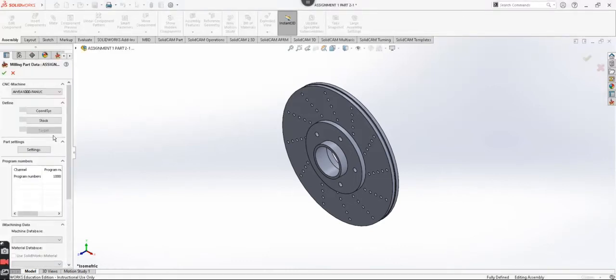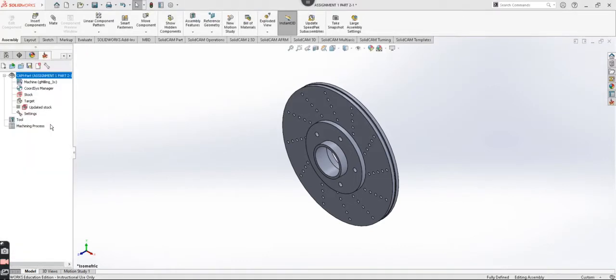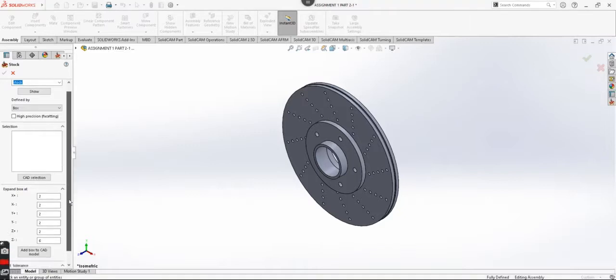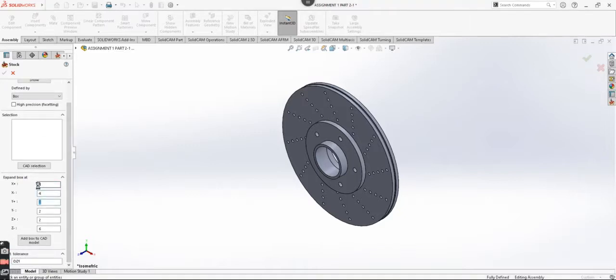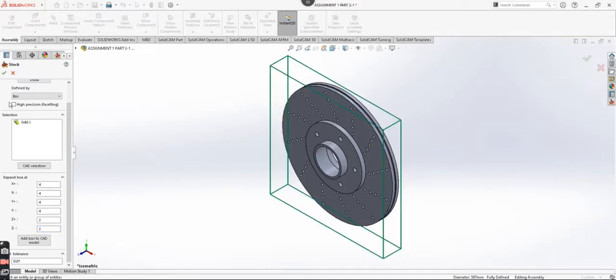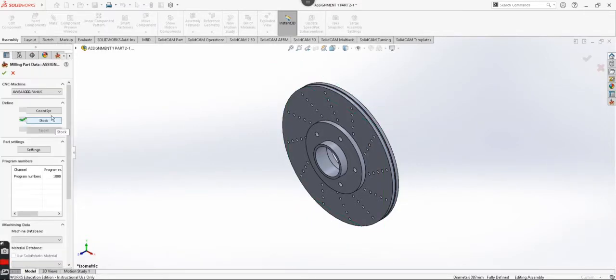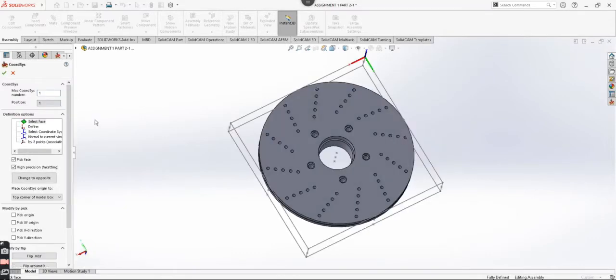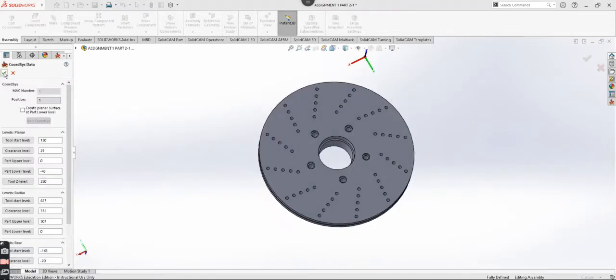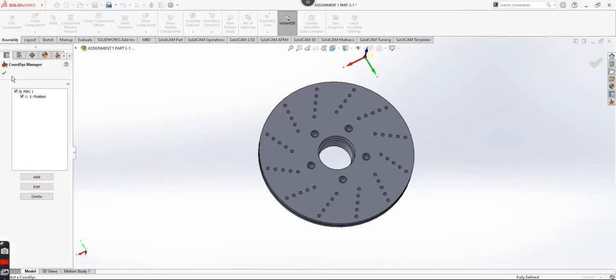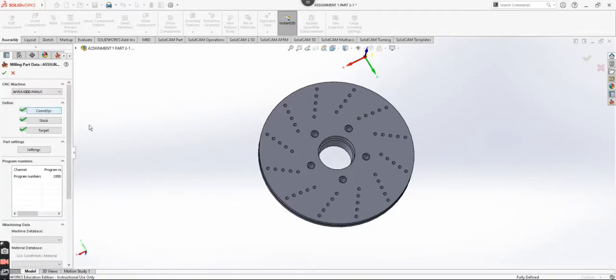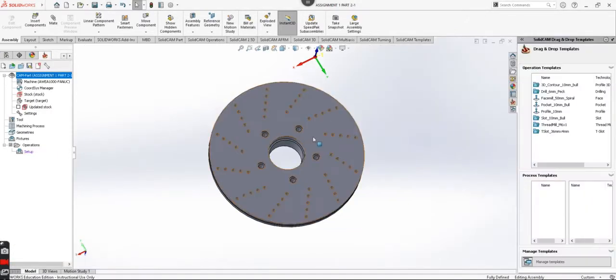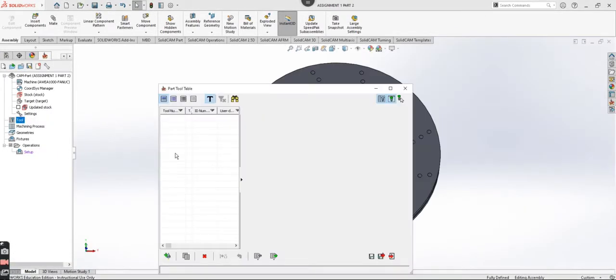So I start off making this part by creating a new milling list. In this part, I make the stock material slightly larger around the X, Y and Z axes, and this is just to allow access for cutting. Then to choose a face to put the milling on, I just click on the actual item itself and proceed by clicking OK for all the other options.